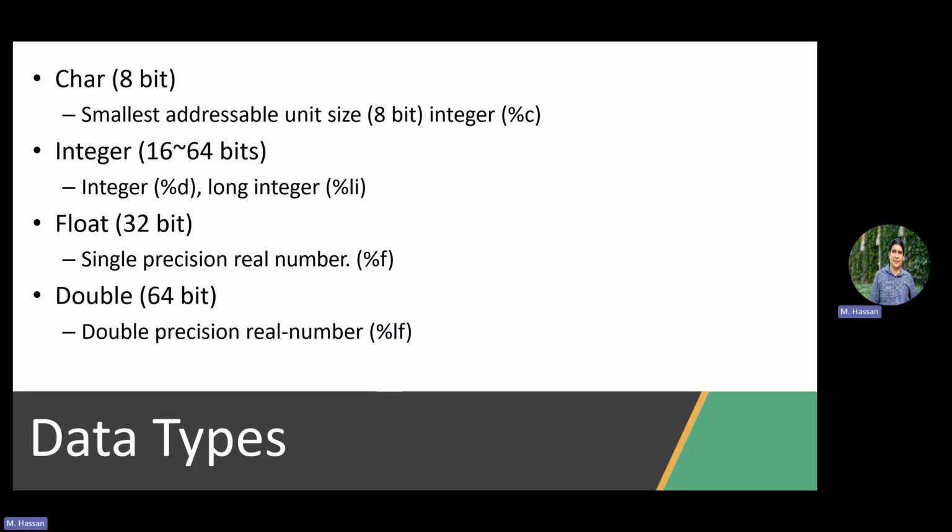Now, data types in C, why is it important to review in embedded? Because, as your friend said, I need to be very well optimized for memory, right? So assume, for example, I want to access certain bits in a register that I know will only ever be 8 bits. It doesn't make any sense to define a variable that is an int, because your int can be 32 bits, but you're only going to use 8 bits. So you're wasting how many bits? 24 bits for no reason, right? 75% of your memory is wasted for this variable for no reason. So you need to be very aware of how you define your variables and types in embedded.